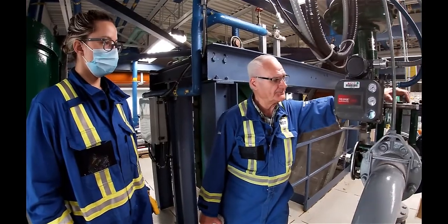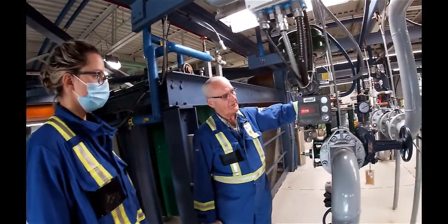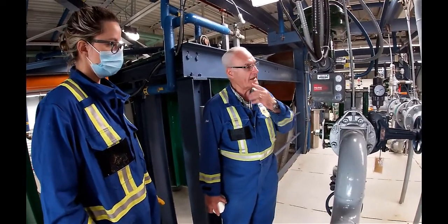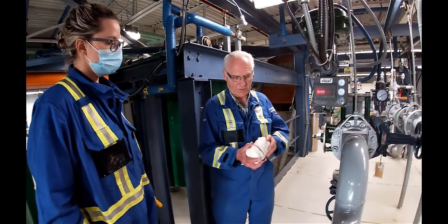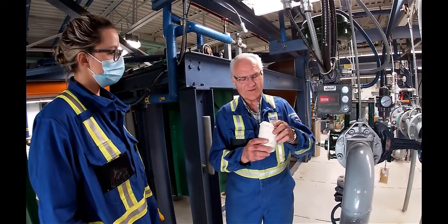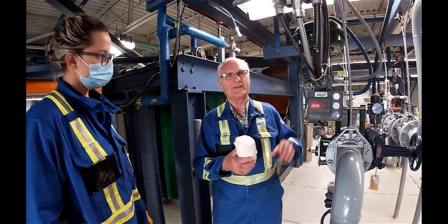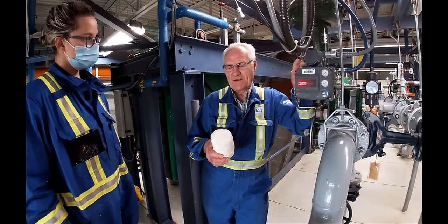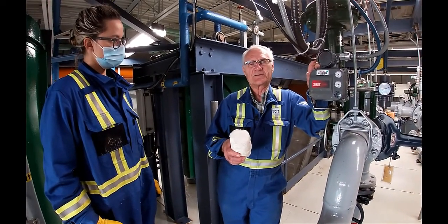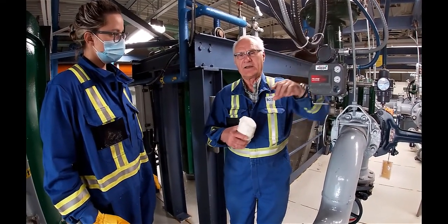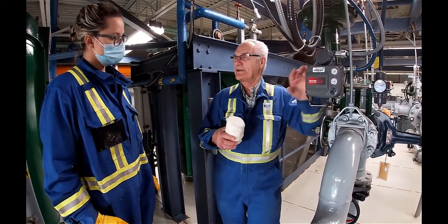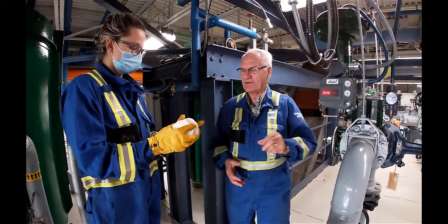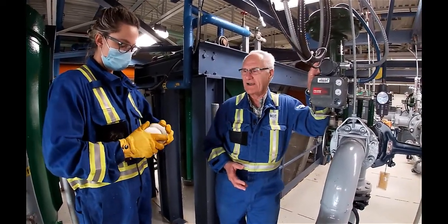What can happen is that, particularly if you start back up again and you've got a valve that's almost closed off, the stock will stay behind and the water will move out. It will form what we call a Presto log, the kind of thing you buy in the hardware store to put on your fireplace or campfire. It's sawdust that has been compacted with a little bit of glue in it to hold it together.